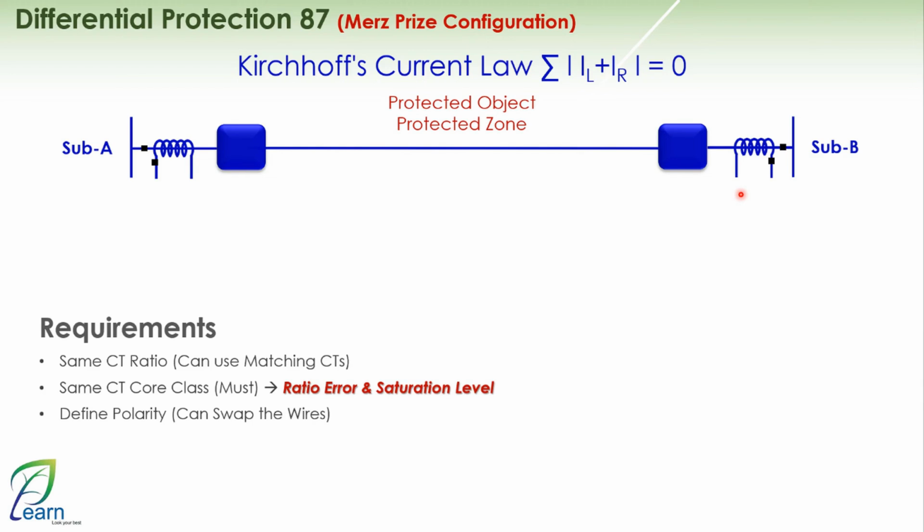Okay, here you are telling me not before 20, and here you are telling me not before 10, meaning not before 10. If it happens at 15, you have no problem, but the one not before 20 will happen above 20. So, is it logical that when a current passes, for example, 12 times, 13 times, one CT will enter saturation? Of course, the other will not enter yet. And therefore, the wave of this CT will be distorted. And this is not correct. So they must both have the same class.